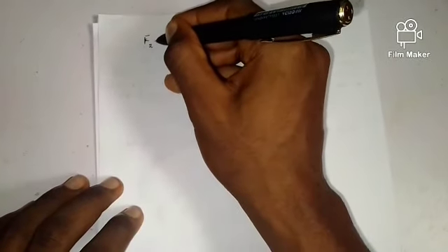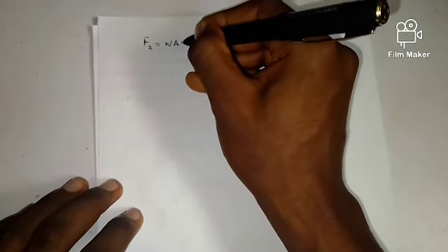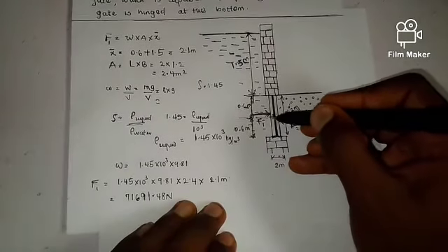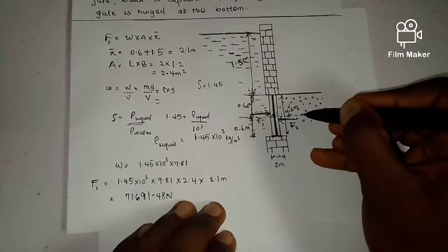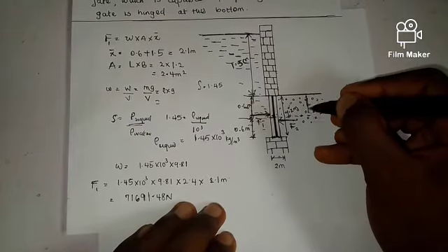We're going to be working with the same formula, which is weight density times area times the depth, right? So now, what's my depth? The depth due to the water here, remember, the depth of the medium will come from the center of gravity, acting from the surface of the liquid to the center of the medium.